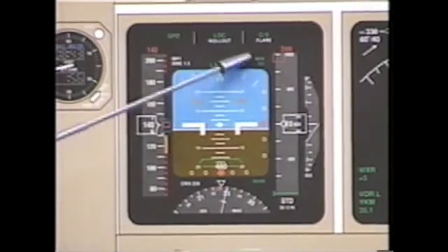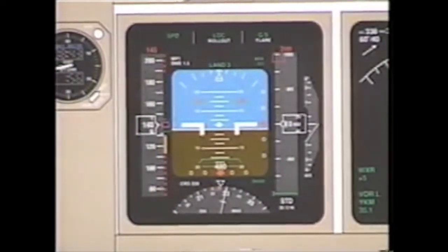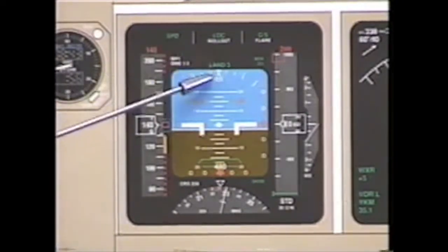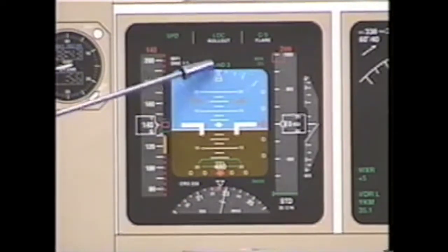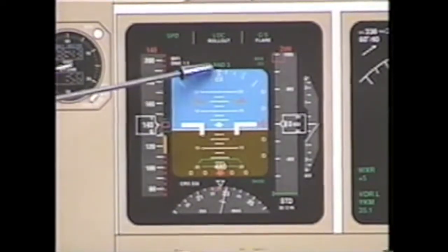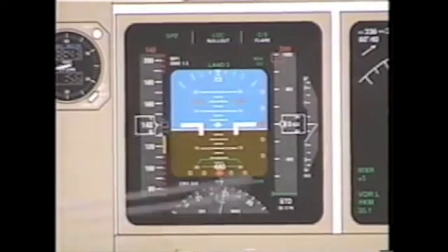As far as autopilot flight director status coming down final, regardless of the number of autopilots we have selected engaged on the mode control panel, this indication on the FMA tells us how many are engaged. Example, let's simulate that all 3 autopilots are selected on the mode control panel. However, this indication is FD, that's flight director, and as a result, no autopilots are engaged. If this says CMD, 1 autopilot is engaged. And if you have a flight director displayed, you know it's not this autopilot.